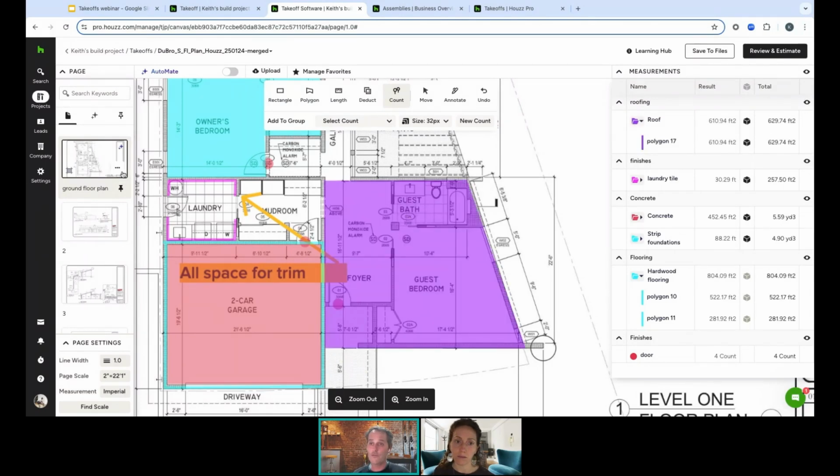Or we can jump over here, as I was mentioning, and clone the page. That gives you a fresh page, which is a copy of this plan, which you can rename. You might rename it carpentry takeoff or roofing takeoff or electrical takeoff. Then you've got a specific page that you can share out with the subcontractors that are coming in to do the work. So that's a couple of ways you can go about it.